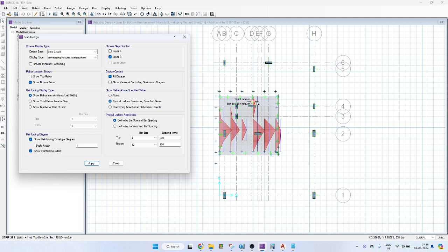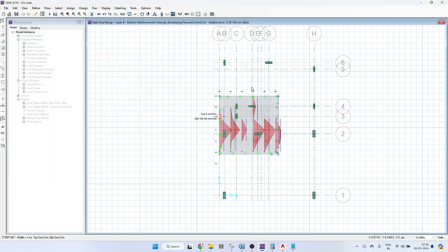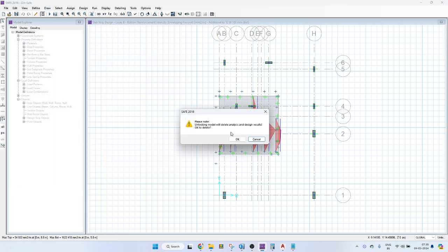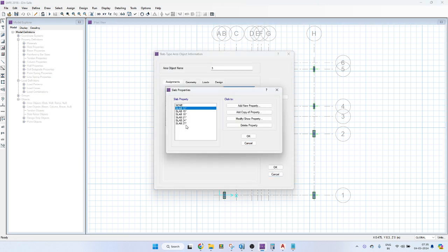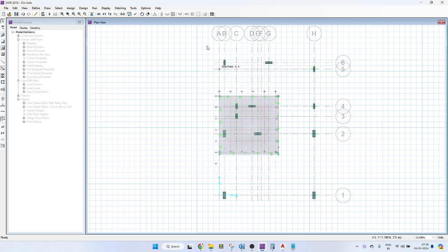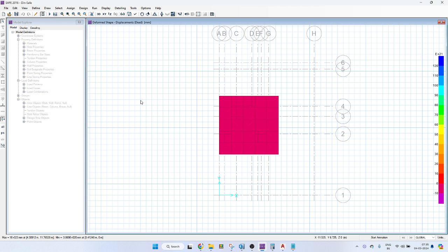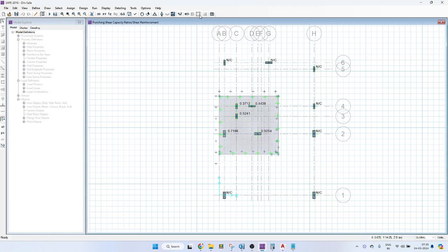We have to put a beam here. We'll put a beam and see. Before that, we correct the punching shear problem. See, if we increase the size also, previously you are getting, no, this is okay.